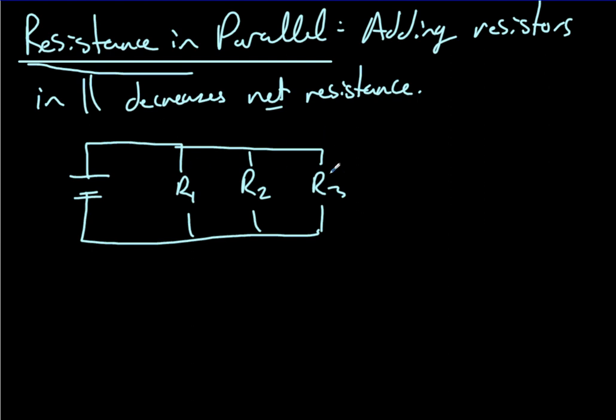With parallel systems, though, all the lights get the same voltage across them, and therefore they'll run just as if they were the only thing in the circuit. Okay, so this is the way it's done. What has to happen, however, is the amount of current gets higher and higher as we add more and more pathways for it through the circuit.